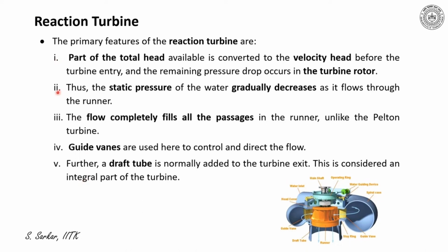Hence, the static pressure of water gradually decreases as it flows through the runner. The flow completely fills all the passages in the runner, unlike a Pelton wheel.